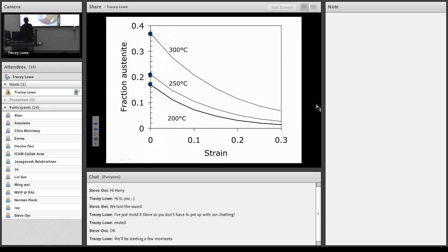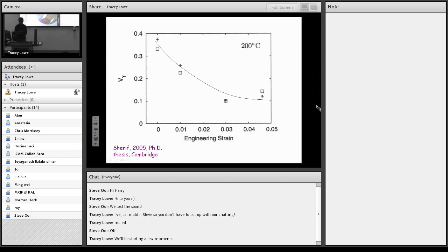And when we look at the point where these samples break, and we've done this also in situ in a neutron reactor so that we can follow these curves as they happen, basically, they all fracture when you reach a retained austenite fraction which is about 0.1. So what's magical about this 0.1? This is the in situ experiment inside the neutron diffraction kit, where we pull the sample, and again you can see that fracture actually happens when the austenite content decreases to about 0.1.